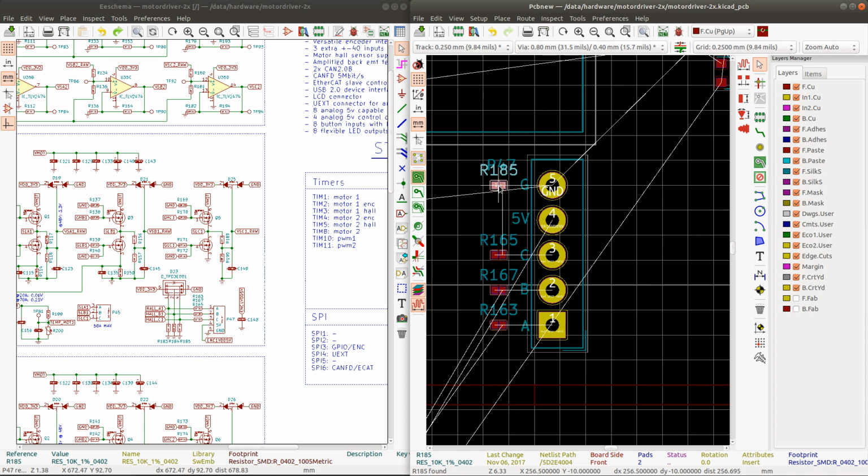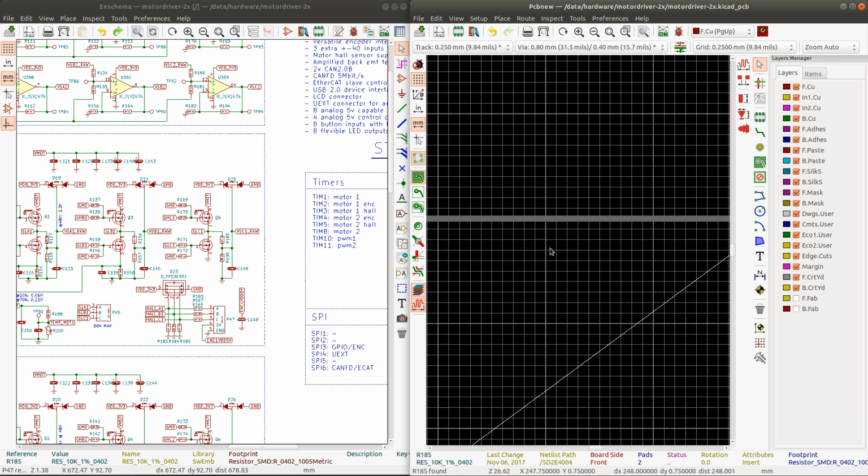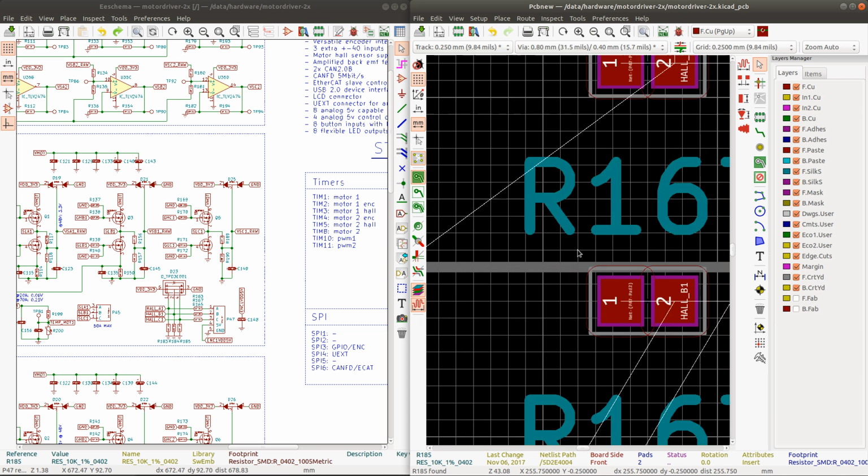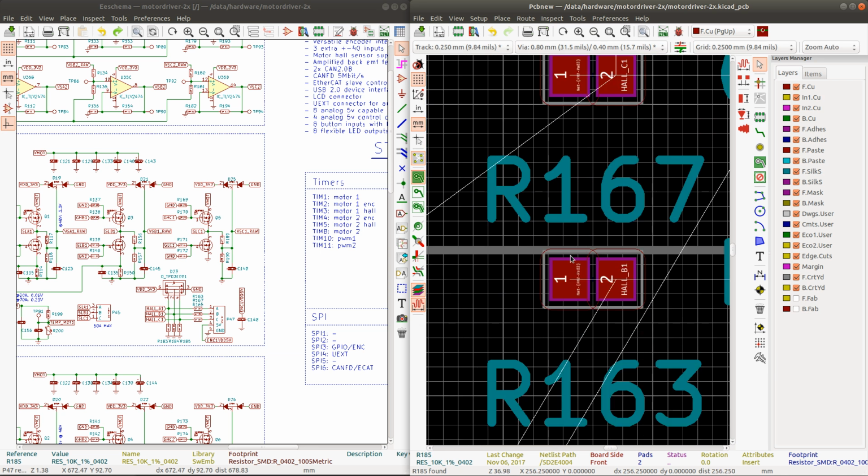I have the courtyard. The courtyard is this gray part here. It's quite small for some components, because this is the default footprint that is provided by KiCad. I have made an attempt to generate my own footprints, where I had a courtyard determined in a similar way that Altium does it. So I had like 3 different variants with different courtyard around them.